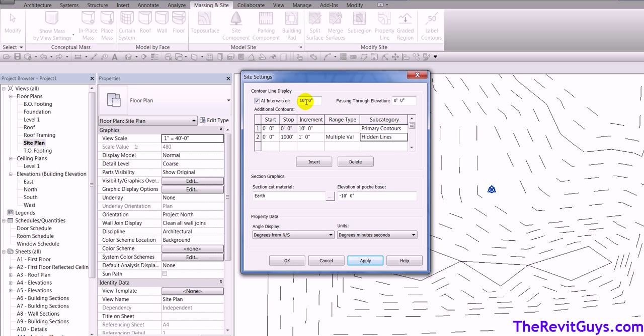You can also adjust the increments. You can say, well, how about every 5 feet? Okay, 5 feet. And at this point we hit apply on that, and you'll see how it changes the numbers. So I have a solid, 1, 2, 3, 4, 5, solid, 1, 2, 3, 4, 5, solid. So we adjust how these things set up. So you can adjust this however you like.